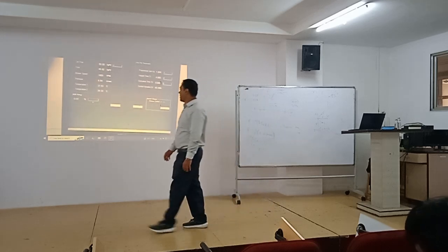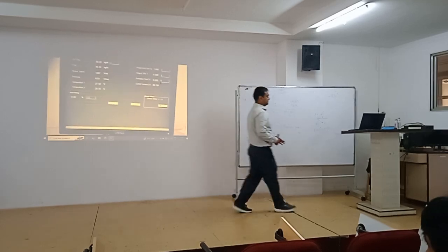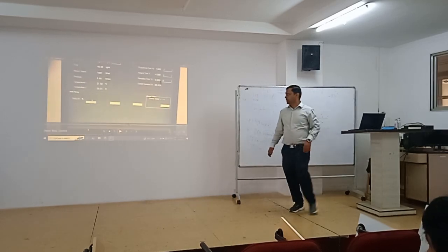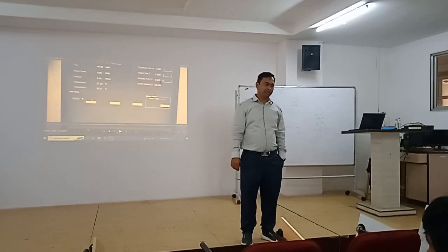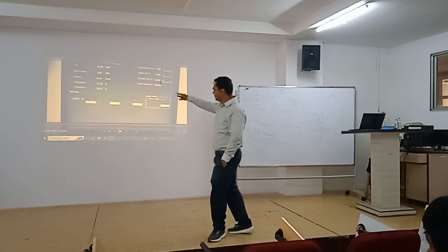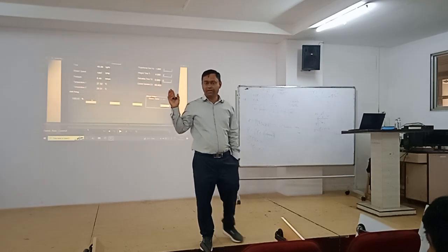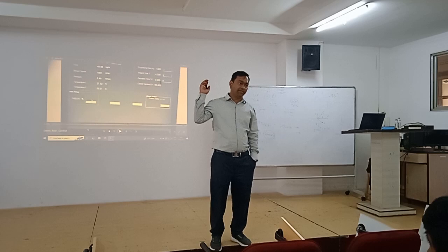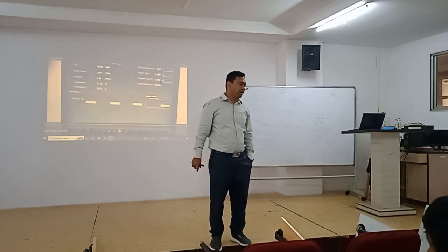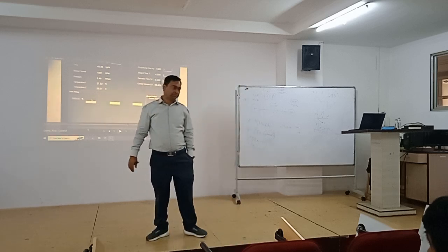So now, what are we doing? Now we are going for second phase. So we are increasing the temperature. Okay, so we are using SSR. Do you know what SSR is? Solid state relay, right? So actually we are using SSR, and by using SSR we are making the heater on 100% firing. So we are giving full support to the heater, right?